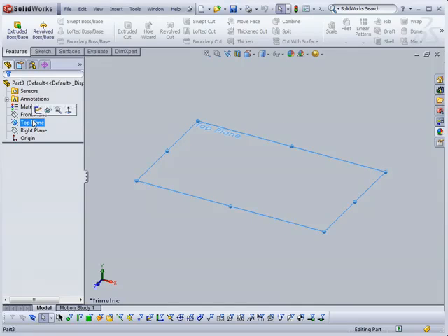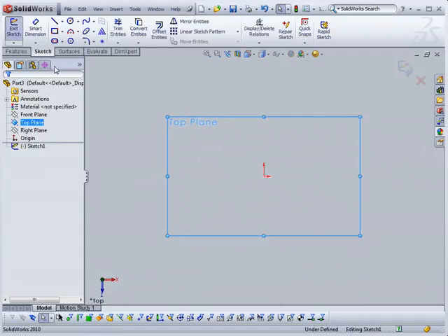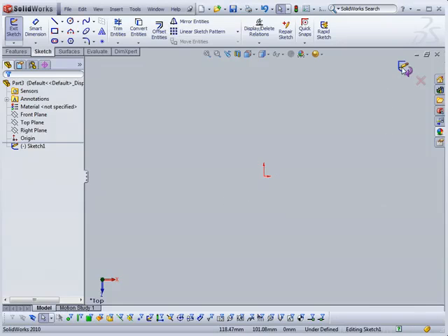We're going to look at the top plane and click on, under the Sketch tab, the Sketch tool, and that will put us into kind of a top view here with a red origin in the center of our sketch, and you can see our sketch exit buttons are up here, which tells us we are in a sketch. Now, parametric tools have parameters that drive them.